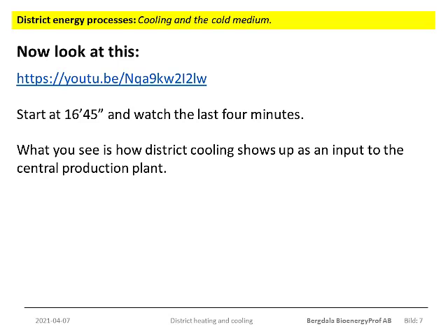What you will realize is that offering a cooling service to customers using an absorption heat pump is radically different from the delivery of heating and electricity. While heat and electricity are plant outputs, the cooling becomes a plant input. So it shows up completely different in the plant energy balance.